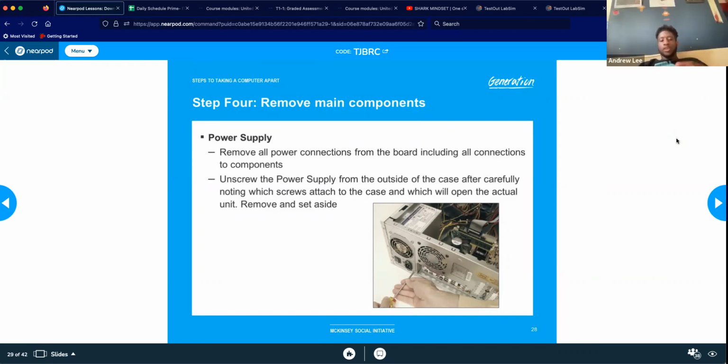Are you keeping everything in their own separate electrostatic bags? Correct, because we don't want to stack things, right? So like if I have two cards of RAM, separate bags? Yes, or if you have a nice clean work area, you can kind of lay them out next to each other, just not touching. So you can lay them out on your mats. Like I have a silicone mat that has like, you know, ESD. And so I will lay all my components out on that mat, and they tend to be safe that way. So it depends on what you're working with.